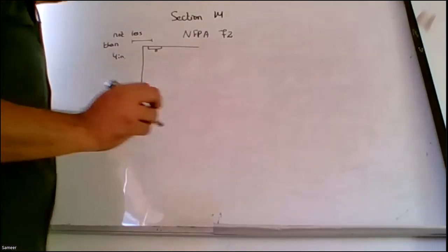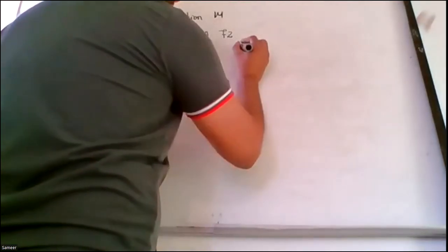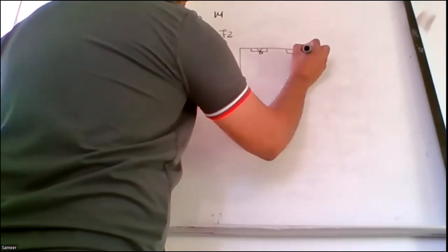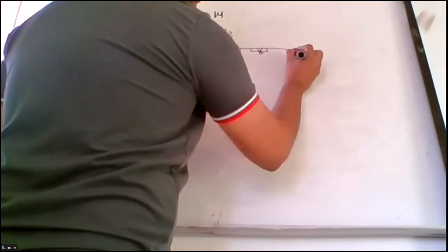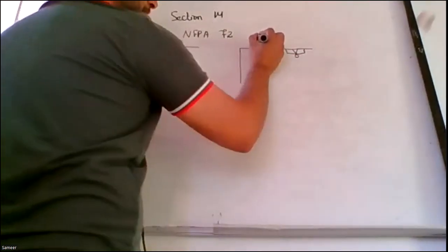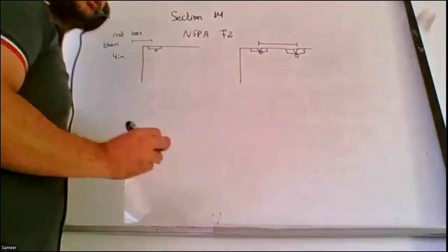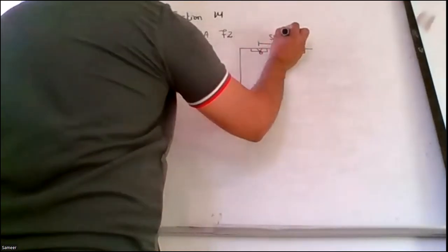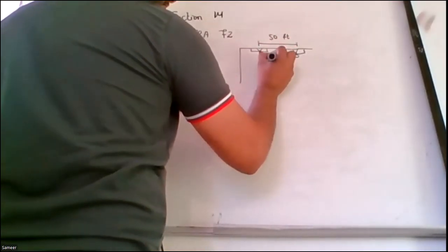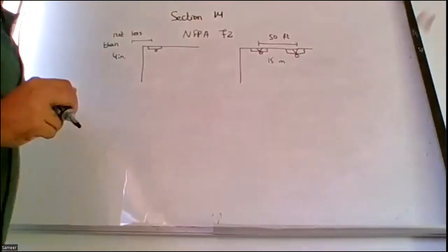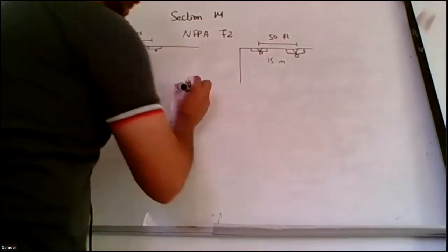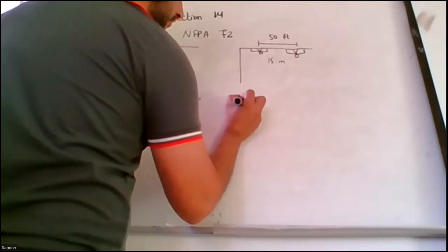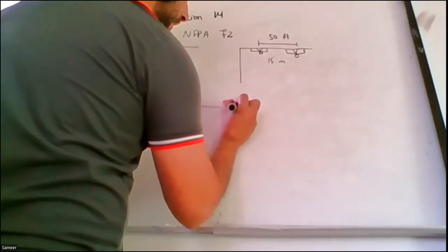Then if you have a combination detector of smoke and heat, the distance between one smoke and heat combination detector and the next should be 50 feet, approximately 15 meters. Usually the common distance between smoke detectors is 9 meters apart.